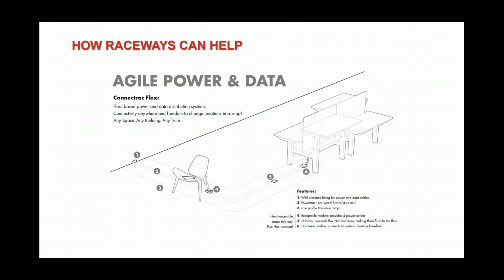If there's a concrete column, or maybe an old facility that has asbestos and you don't want to go inside it, you can do it as a surface mounted. So we're going to start at that wall. Number 2 on this picture is a wireway. That's our raceway coming down through the middle of what you see. And that's a raceway that runs either pre-wired power or something that an electrician is going to place wires in.